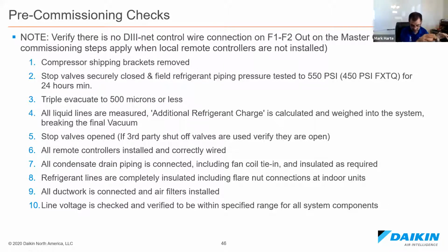evacuation. Evacuation is key. You've got to do a good evacuation. If guys aren't using micron gauges, and there are so many different evacuation pumps out there nowadays, with oil you can change as it's running. There's no reason not to do a good evacuation. The better the evacuation, the better that system's going to run. Trust me, I've seen so many issues where guys don't do it properly and they have problems down the field.